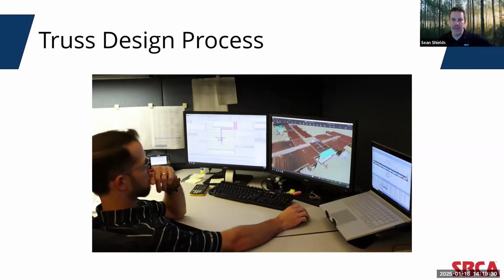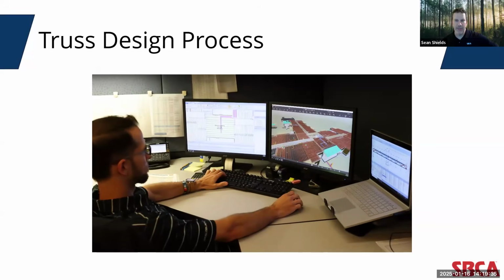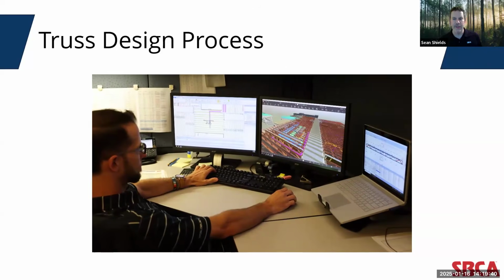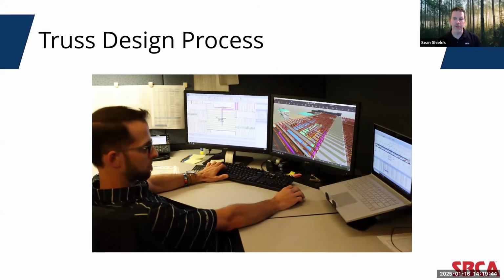And occasionally, the truss designer will determine that a truss simply isn't possible given the initial design criteria. In those cases, the manufacturer will typically go back to the customer or building designer to suggest alternatives, such as spacing trusses closer together, or, let's say in the case of floor trusses, increasing the floor truss depth. The point is that with today's robust design software that we just talked about, the options available to a building designer are virtually limitless, as long as they are pursued with the component manufacturer prior to the start of construction.